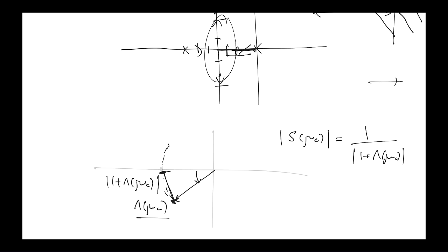So if the phase margin is small, this will be small and the sensitivity function will peak up. Whether moving the crossover frequency to different points causes this depends on whether it changes the phase margin in a way that makes it bigger or smaller. Both can happen. But if you understand the meaning of all these things, you'll be able to interpret what happens, and that's the important thing. Make sense?